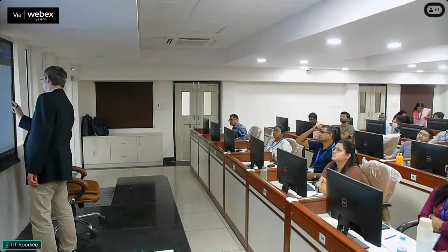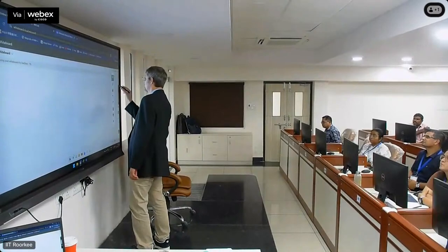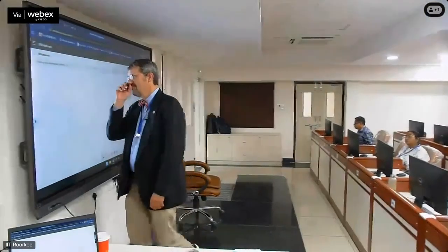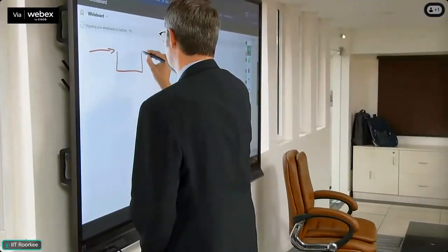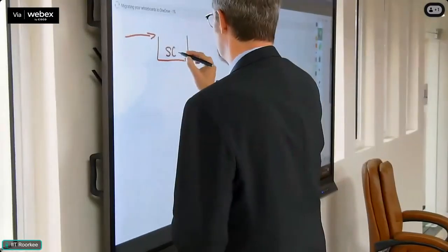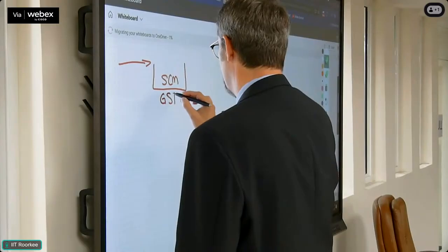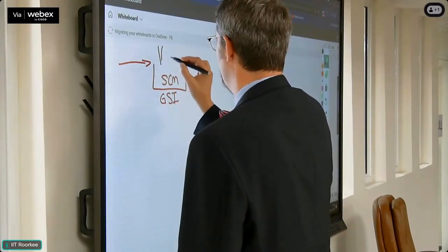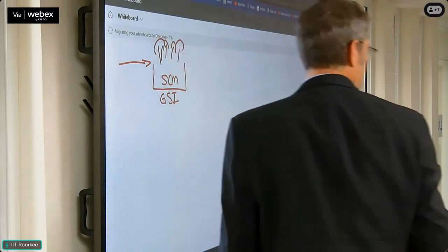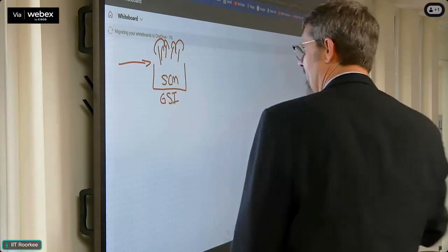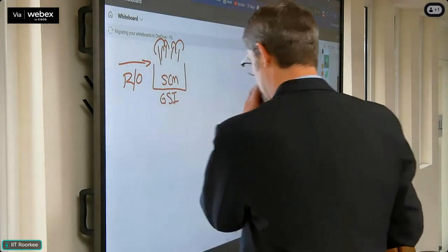It accommodates only 60% approximately. Then we have runoff coming into a stormwater control measure, or SCM, also known as part of green stormwater infrastructure. 35 is coming in, 80% is coming, and runoff is coming into your stormwater control measure.